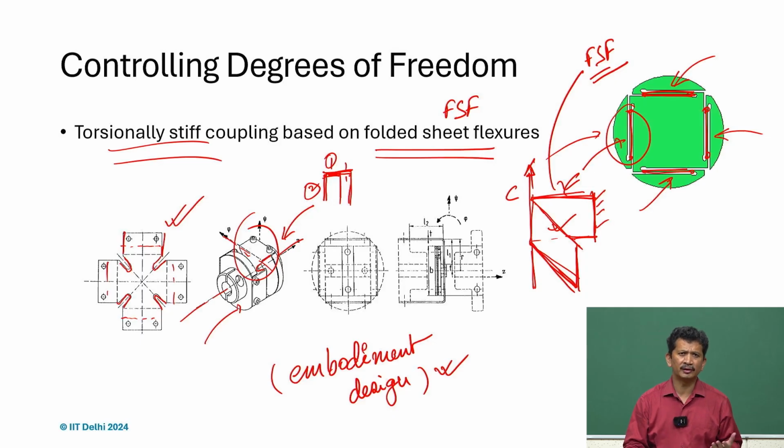So, again the maintenance, wear and tear, lubrication, all those things can be easily eliminated, and therefore it can be used in a very rugged environment as well, even for solar applications. Suppose you want to design solar farms and articulate the joints and run the entire farm with only a few motors, but what about the coupling? You may need to couple each unit. If you are not aware of these things, you may be going for those kinds of solutions. But if you are aware, you know that simple sheet flexures can work, you can make them out of sheet metal, just bend it in this way and attach it, and you get a very good solution.